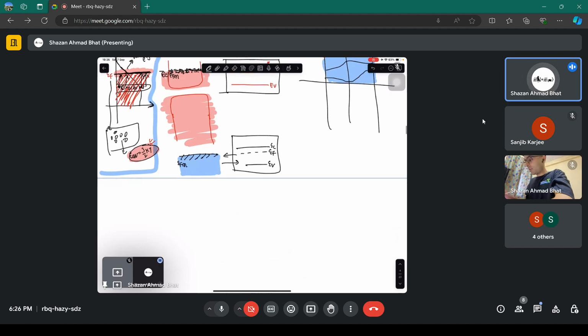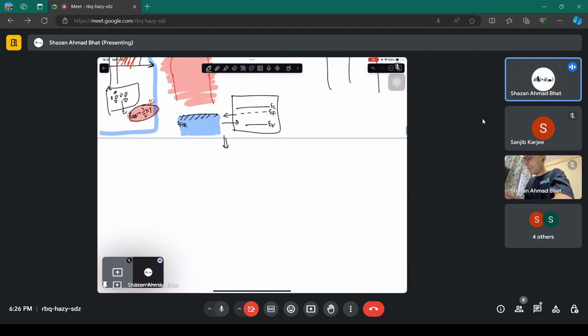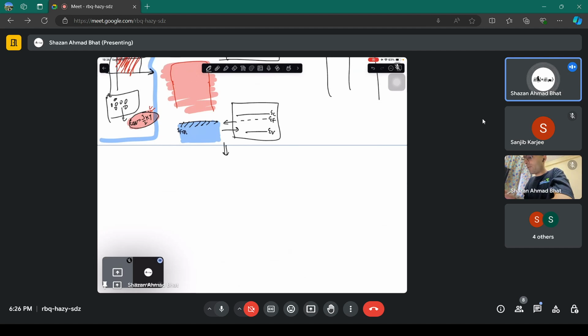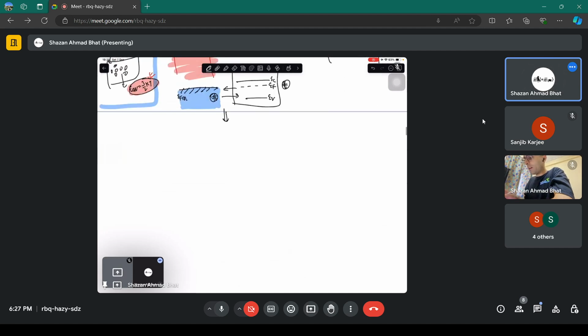When you just make a contact, it depends upon a few things. It depends upon whether the Fermi level of this metal is greater than that of the semiconductor. Or rather, there is something called the work function. Say you have the Fermi level of a metal, and a semiconductor with its own Fermi level; there is a level called the vacuum level, the vacuum energy. It's the energy which you need to give the electrons to completely isolate them, or make them free, of the metallic structure or any semiconducting structure.